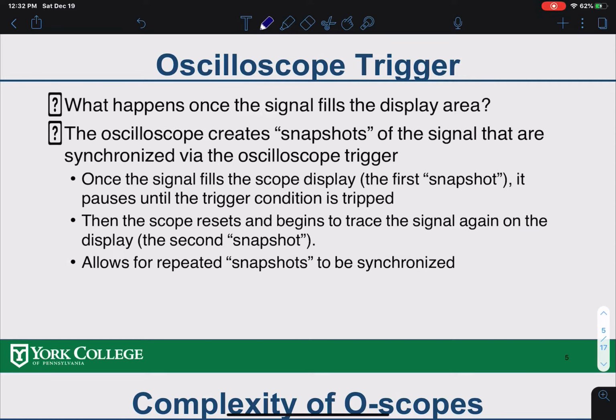For the oscilloscope, one of the very important features is the trigger. What is the trigger? Your time varying signal coming to the screen of the oscilloscope is always changing. So how do you make that signal stabilize on the screen? That is called the trigger. You define the trigger with a time and a moment of the signal to take a snapshot.